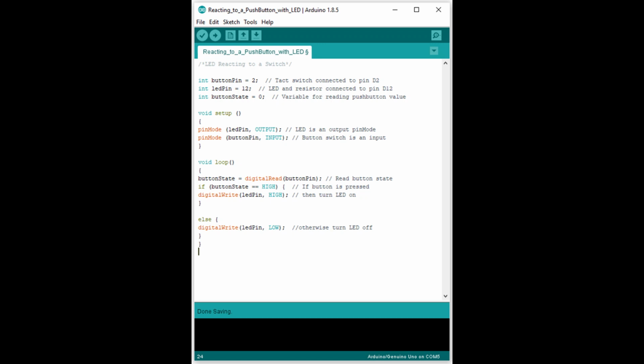Setup(). pinMode(ledPin, OUTPUT) declares the LED pin as an output, ready to shine. pinMode(buttonPin, INPUT) declares the button pin as an input, eager to hear button clicks. 3.